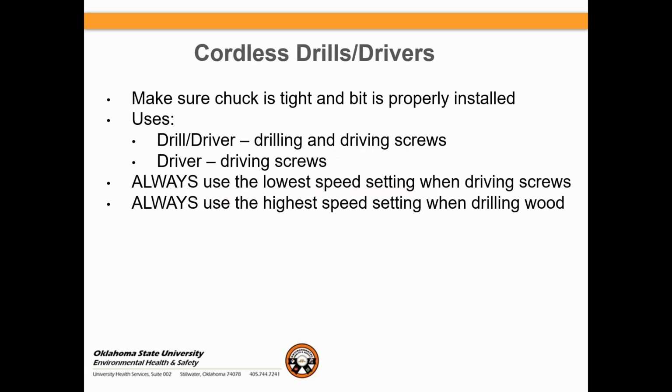Let's talk about the cordless drill. Make sure the chuck is tight and the bit is properly installed. As far as the uses of the drill or the driver: drilling and driving screws. The driver, once again, is for driving screws directly into the wood itself. Always use the lowest speed setting when driving screws, and always use the highest speed when drilling wood.